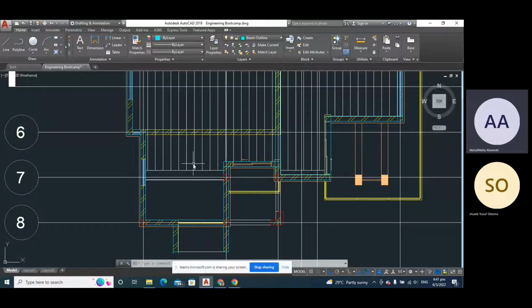So I personally prefer to have an upstand beam, because if it's raining, this slab is going to retain water, and water here might tend to go in this direction. You understand? As the water moves in this direction, it moves into the void, and the void leads to the ceiling. These are some of the mistakes some people make. If you are having a roof slab, it's always advisable to have an upstand beam around it, and after having the upstand beam itself, you are still going to waterproof it.